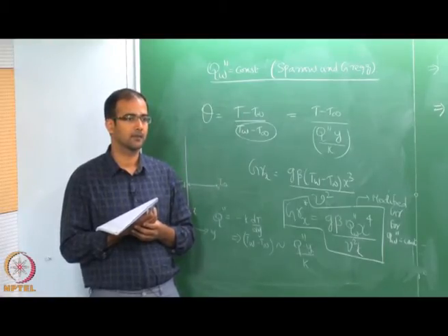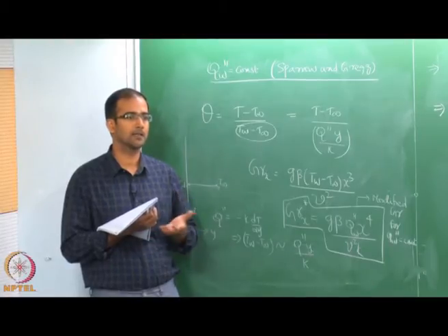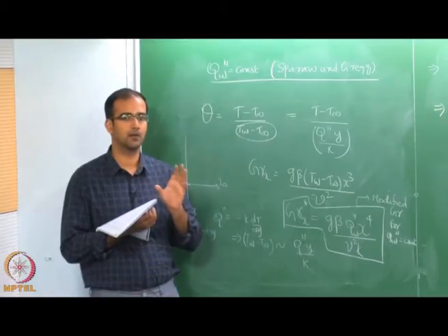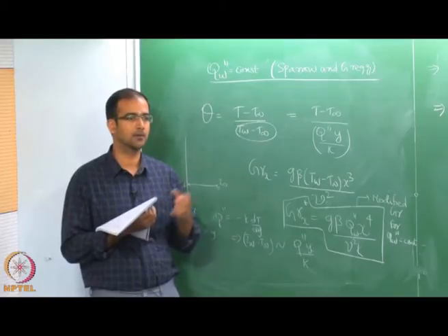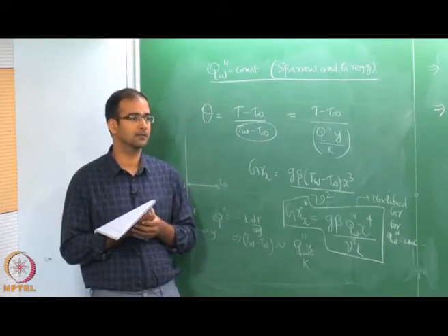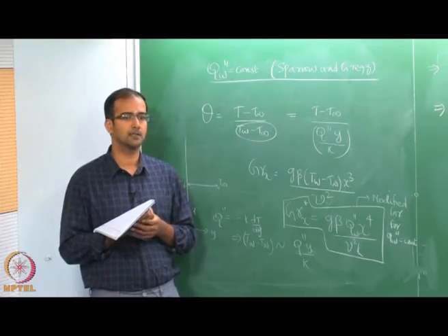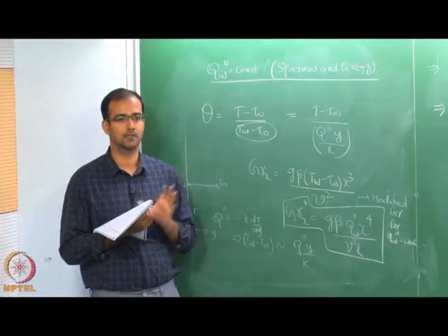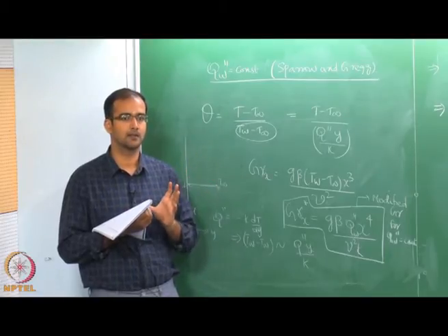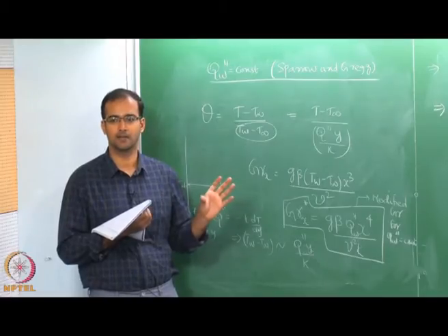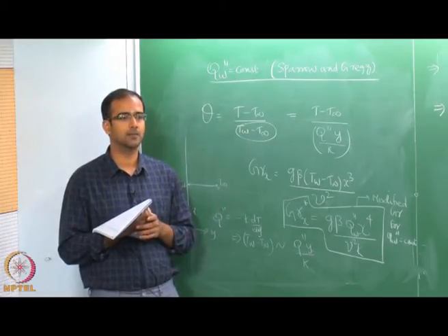Can we use y there or some delta? Why do you want to complicate the definition of Grashof number? The Grashof number is only based on one local coordinate. Why should we use y times x? How do you then compute your Grashof? Is it a 2-dimensional variable? The Grashof number is just a local coordinate attached to the plate length. We cannot define a 2-dimensional Grashof number here, it is like defining a 2-dimensional Reynolds number.